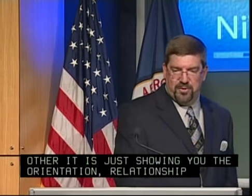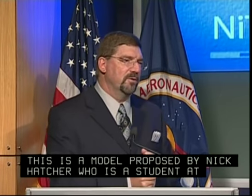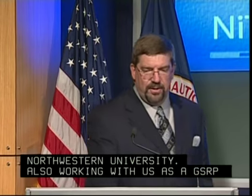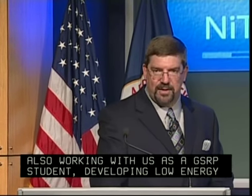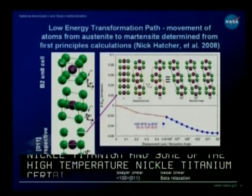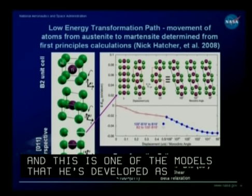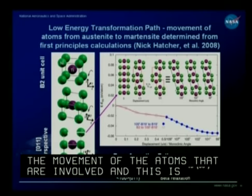This is a model proposed by Nick Hatcher, who's a student at Northwestern University. He's also working with us as a GSRP student, developing low-energy transformation paths in the nickel titanium, as well as some of the high-temperature nickel titanium ternary alloys that we have. And this is one of the models that he's developed as far as the movement of the atoms that are involved. And this was calculated using first principles calculations and determination of gamma surfaces.